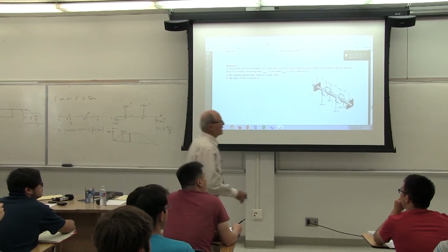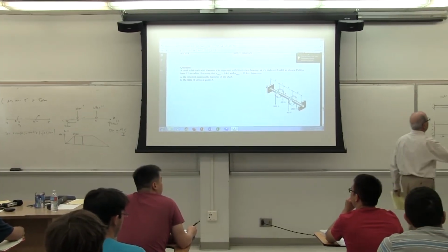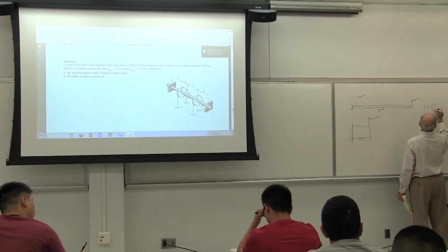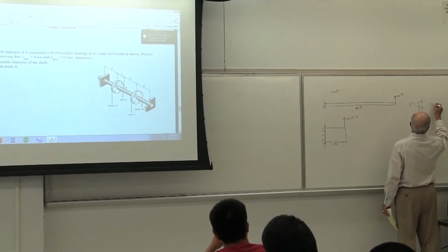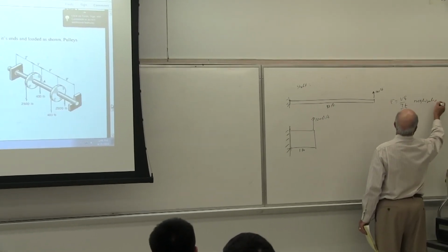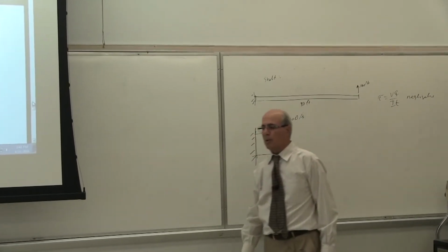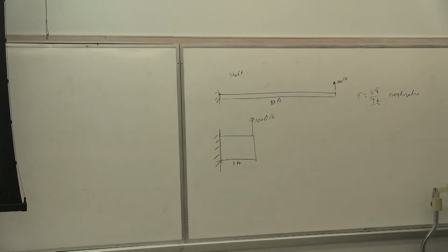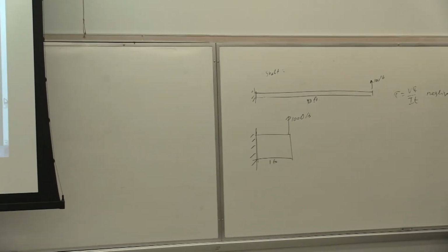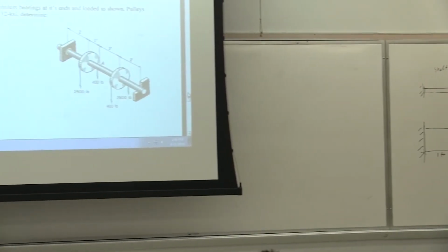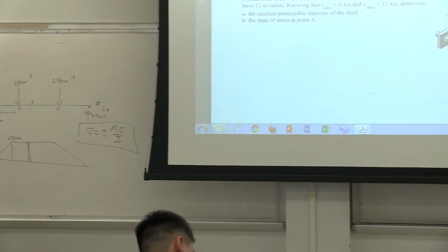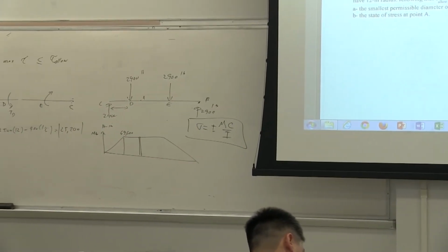So since the transverse shear for this problem, write it down, tau equal to VQ over IT, is negligible compared to the other one for this type of problem. For this problem, even if you have a shear diagram here showing some shear, we are going to assume so. For the shaft design, we only consider the stress due to the torsion and the stress due to the bending. This is the bottom line. Write it down in your notes.